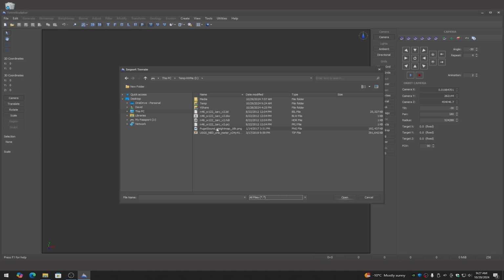So for example, in Photoshop, if it was using the values between 0 and 32,000, TerreSculptor will normalize that to 0 to 65,535. You would then use the terrain properties for scale to be able to get that elevation range back out of it, or use the altitude modifier and modify it back.